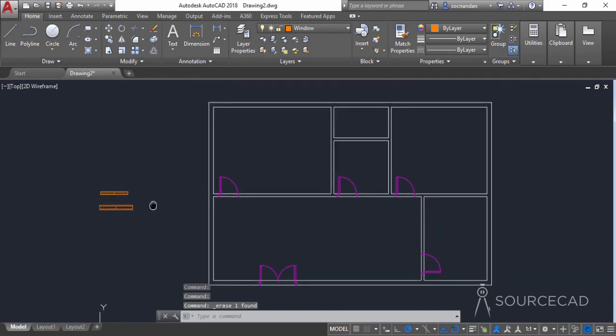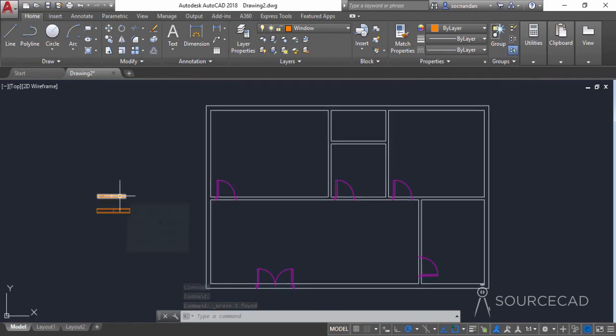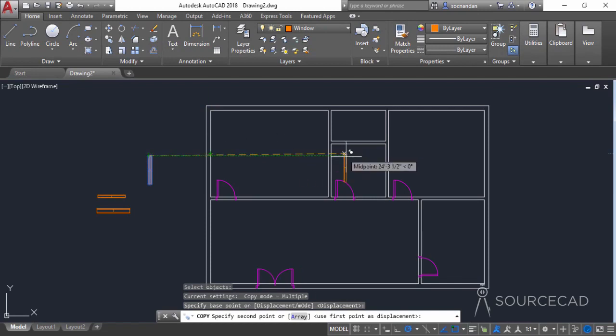Now we have these two windows which we need to add. I'll start by adding this window, but I'll make a copy of this, and I'll first rotate this one. So select rotate and click on this point, and you can directly make a copy by rotating this also. So I'll simply click on copy and make another copy of this which is rotated to a particular angle. You can move it also, here it is. Now select the copy tool, select this one and move it on this wall. Obviously we need to move this second one, as this is the wall of 10-inch thickness, so we can move it inside this drawing, and in this case we will place it here on this wall, just like this,